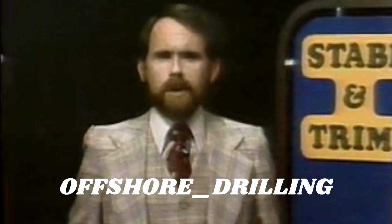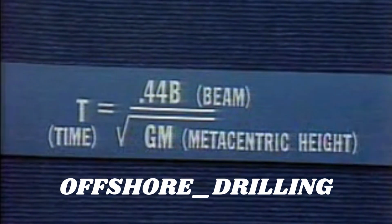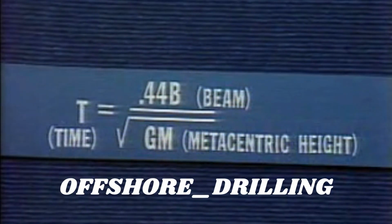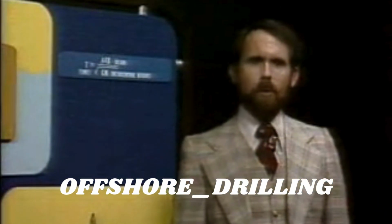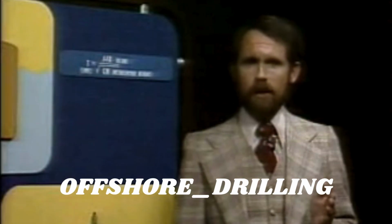It can be roughly calculated even before putting to sea by using the formula T equals 0.44B over the square root of GM, where T is the rolling period in seconds, B is the beam of the vessel in feet, and GM is, of course, the metacentric height. It should be apparent from the formula that a beamy or wide ship will have a slower roll than a narrow ship such as a destroyer.